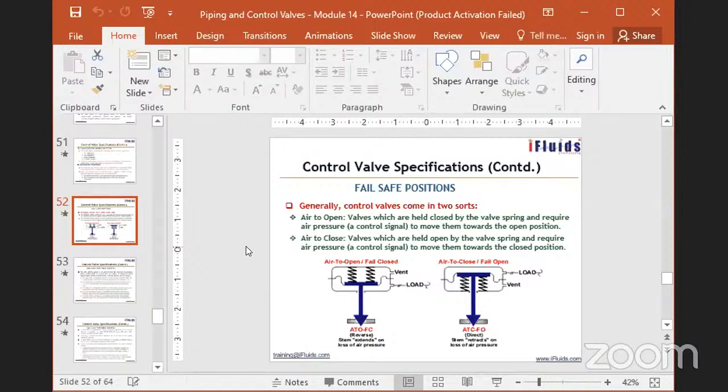They are actually put in a separate location in the same plant. Process units will be in one block, and along with utilities, we have one more terminology called offsites. Offsites is a little away from the main plant, and it is used to store the raw materials and products. If you go to any refinery, you will see huge tanks to store the crude oil, which is the raw material. Then you have a number of tanks for storing the products.